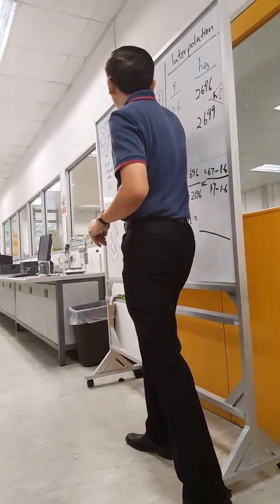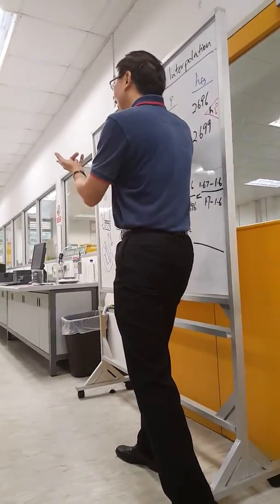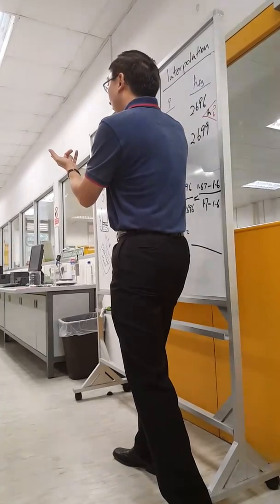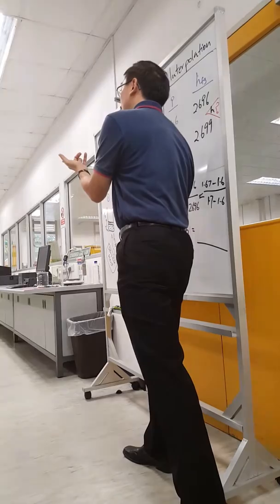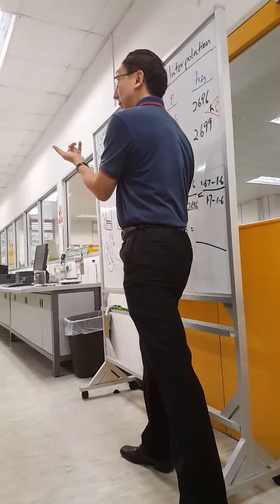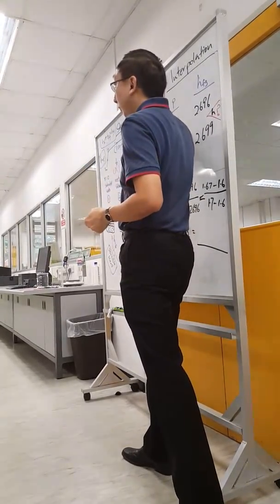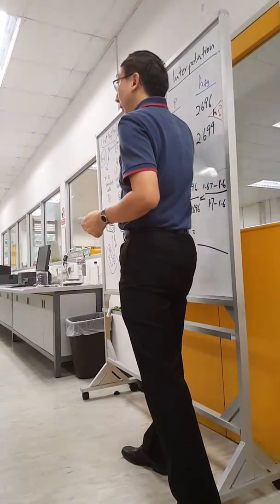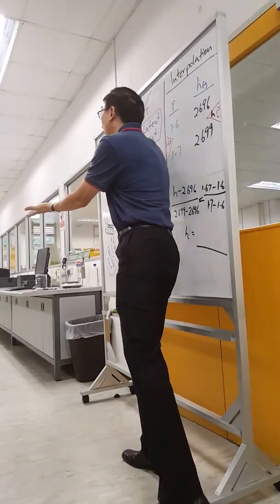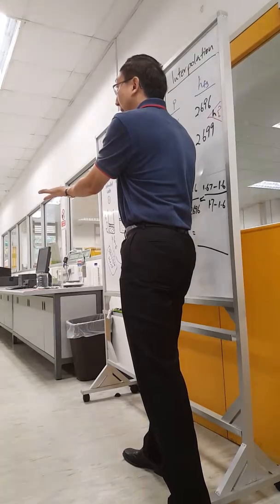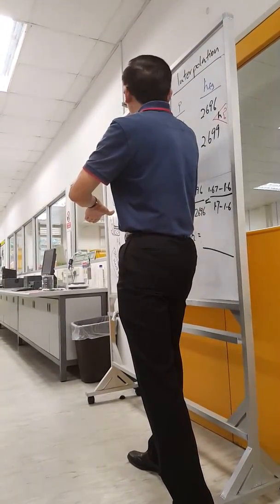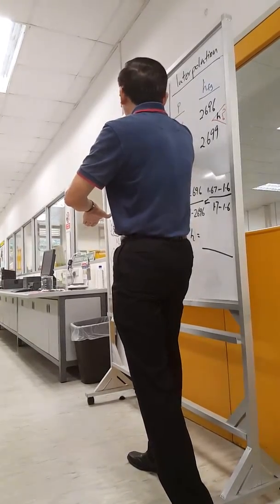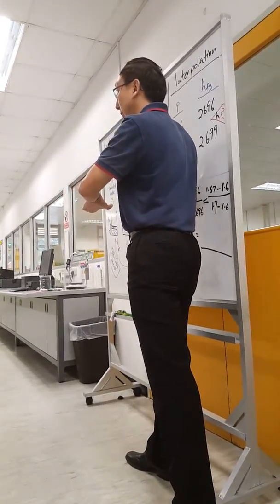If the steam temperature is above 100 degrees, say 110, what do you think? Superheated. You will go into superheat. For this pressure here, the maximum it goes up to here is dry. But for the same pressure, 1.013 bar atmospheric pressure, if it goes above 100, that means it is in superheat now.